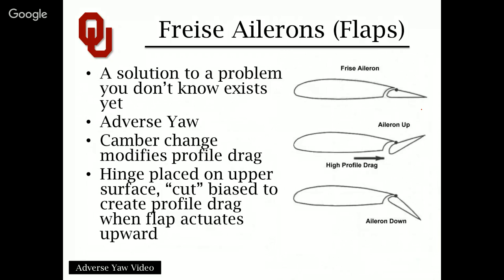So you're trying to roll the airplane left, but you drop a flap trailing edge down on the right wing to lift that wing up, generate more lift on the right side, generating the roll you want, but you've increased drag. This asymmetric drag creates a yawing force on the plane. So the fact that you have more drag on the right side now pulls the nose of your vehicle towards the right. It generates essentially a positive yaw rate.